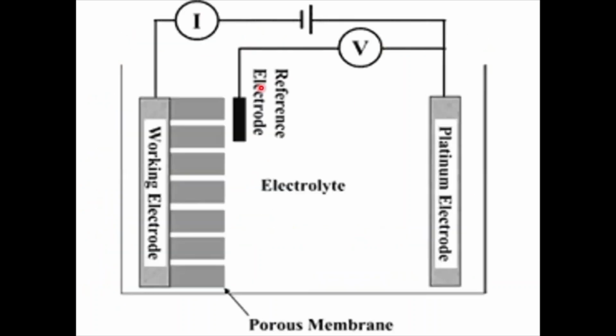Right, whatever the thing, you try to cover the working electrode with the membrane or the template, and based on the electrolyte, right, on the application of galvanostatic or potentiostatic or pulse conditions, you try to get the deposits which are of nano dimensions on the holes or pores. Try to remove the other parts using a solvent, and you can have freestanding nanostructures with a restrictive template assisted electrochemical deposition process.